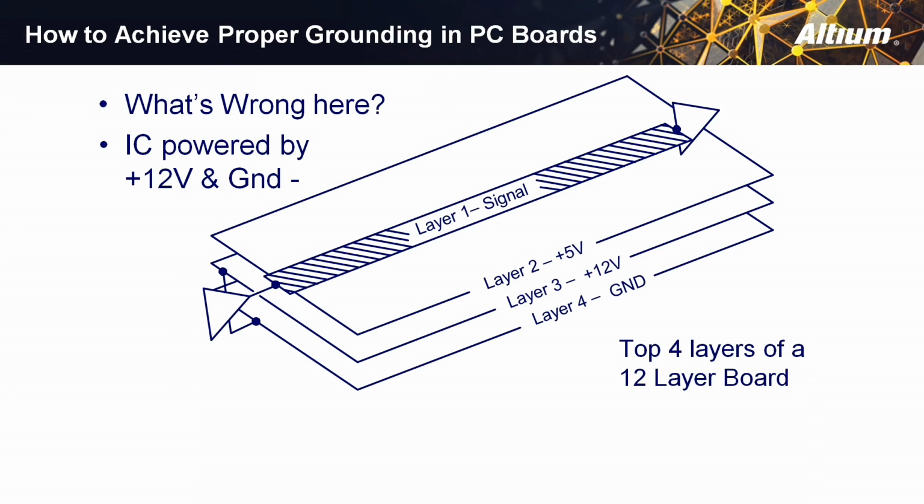And I said, how does the energy get back to the driver if it's returning in a plane that does not connect to the driver? He looked at me puzzled and said, oh, good point. I have no idea. And I said, the energy has to spread out across that dielectric space between 1 and 2 to find holes in the plane on layer 2 so it can couple to the dielectric space between 2 and 3 so it can get back to the driver. That's its only means of returning to the driver. And the end result is the spreading of the energy to find its way back.